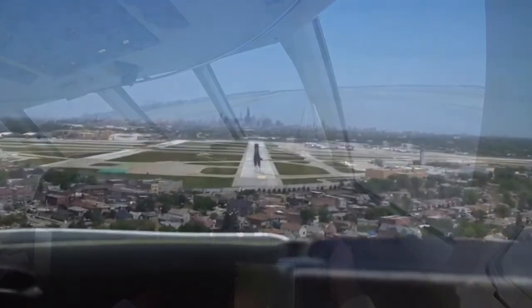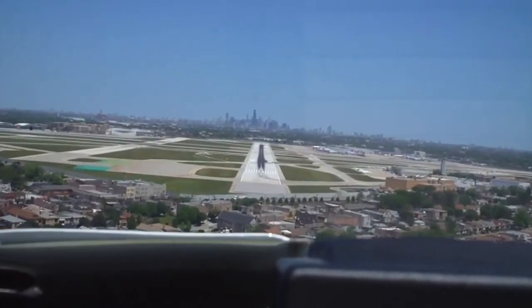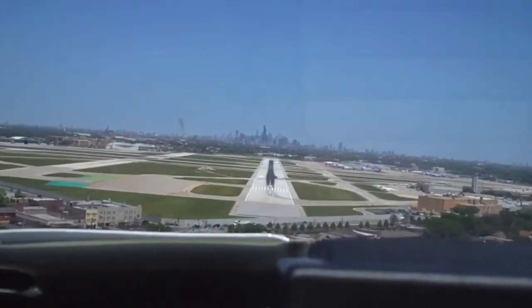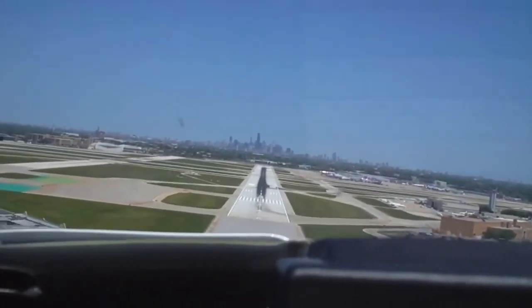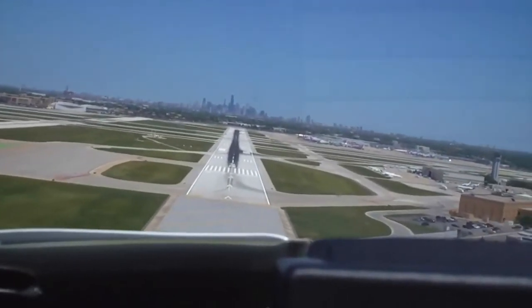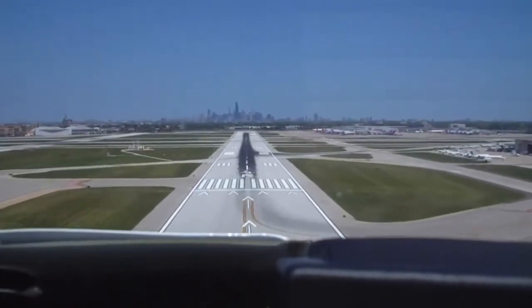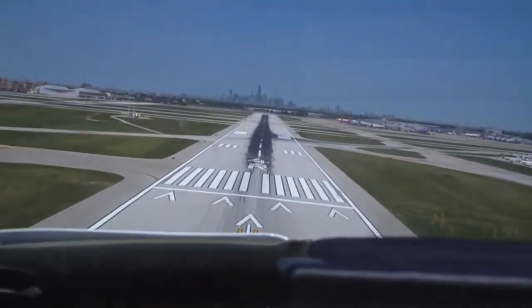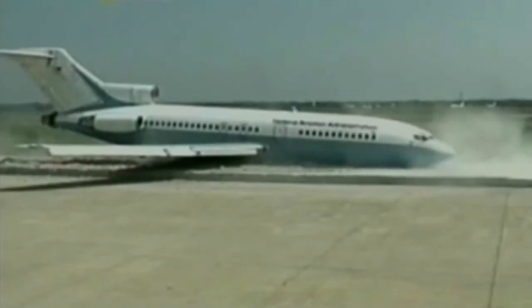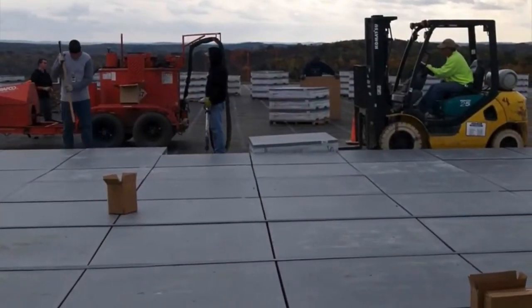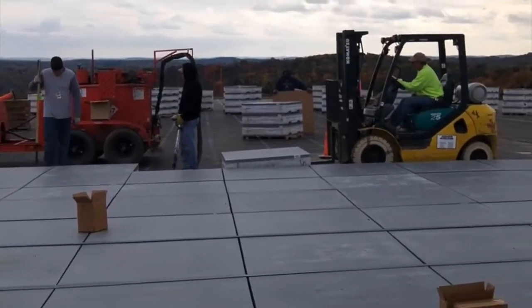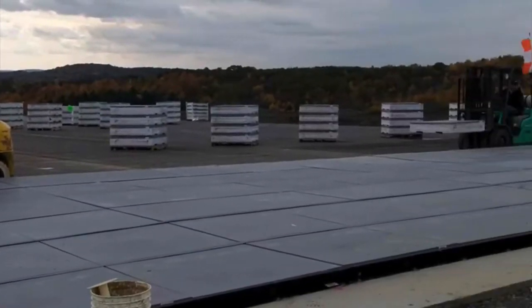Let's take a quick look at Chicago Midway, an airport famous for geographic constraints. Surprisingly, the declared distances are equal to the physical length of the runway, displaced thresholds notwithstanding. How is this possible with adjacent roads on all sides? The answer is EMAS, or Engineered Materials Arrestor System. These energy-absorbing materials, basically lightweight concrete blocks, crush under the weight of an aircraft. This high-speed quicksand stops the aircraft and prevents overruns, usually with little or no damage to the airplane.